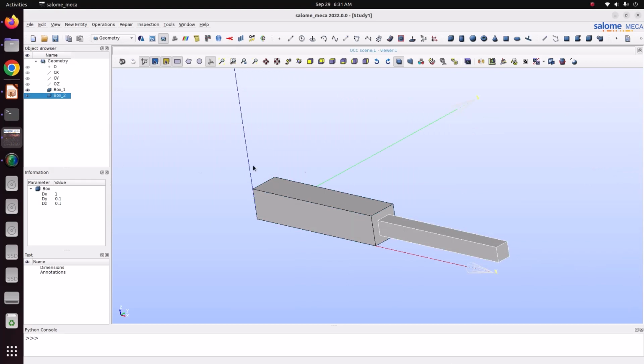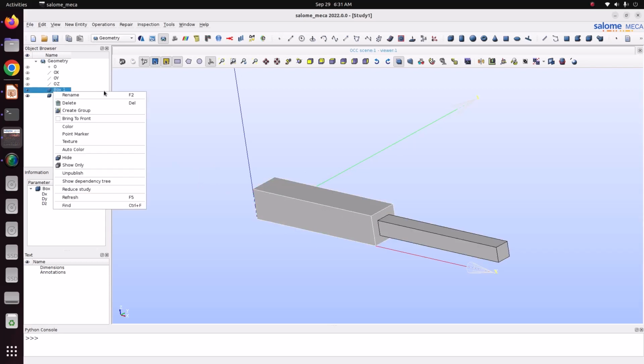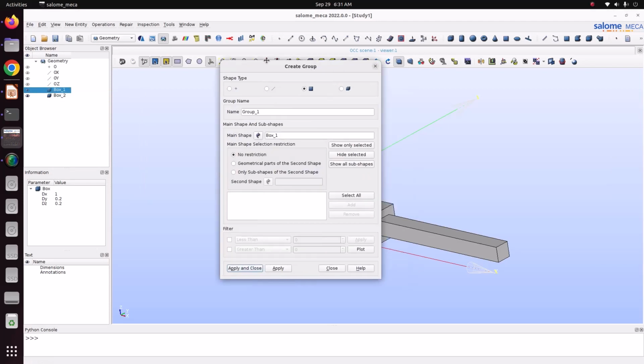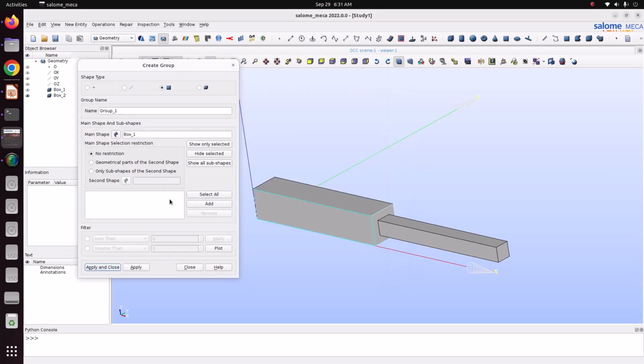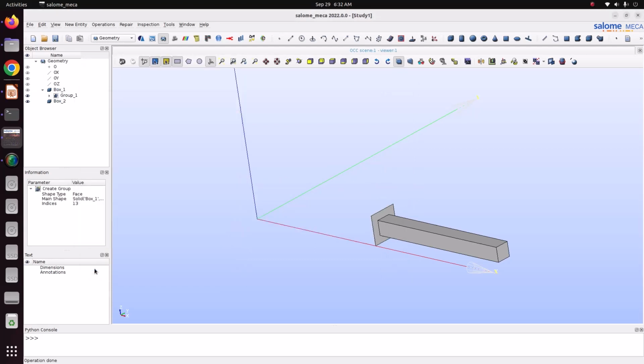Now we can fuse. We can make body into single body. So before that we'll create one surface. We'll see the surface will be used later. I just created this mid surface between these two objects. Then now we'll go fuse this object.